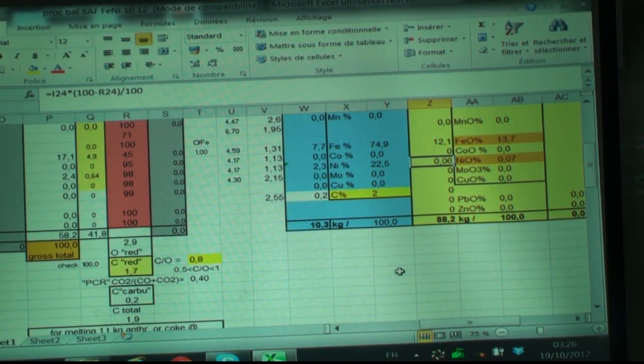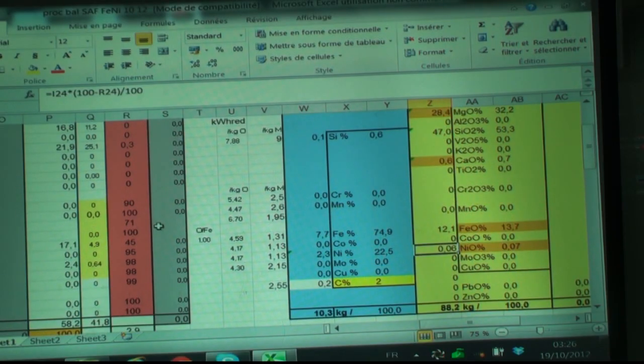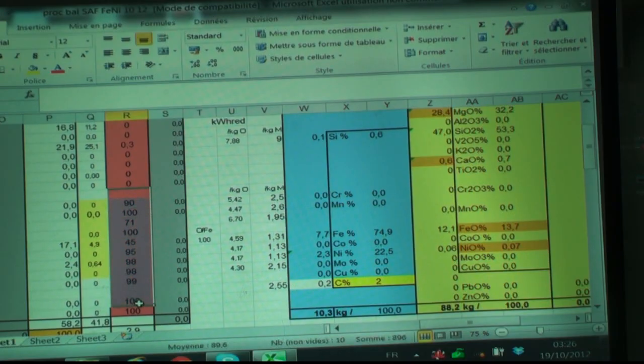We discussed that when we calculate the ferromanganese and ferronickel, we have to use a different Excel sheet, right? No, we could use the same, of course. Everything is the same, but in the case of the FeO in slag, no. This is the key assumption. What may be different is the yield of reduction, and this is more or less experience.